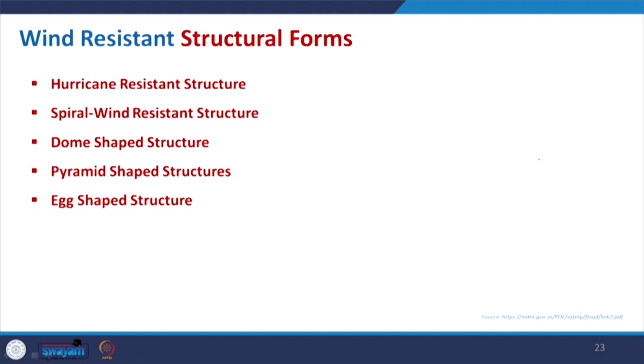Now, based on this we understand that the regular form that we want, the basic shape, should be very much squarish or maybe circular if possible, and again with the height we have to really think of the aerodynamics, and then we can make design for all structure with such structural system which can resist the lateral load due to the wind.